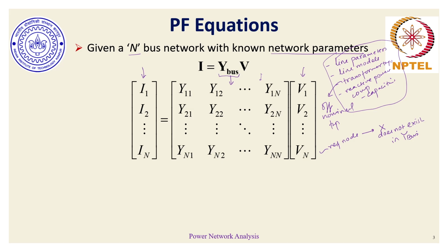So, given this Y-bus, our job is to find a certain set of equations, which we call power flow equations, and from them we will be able to find the corresponding bus voltage phasors. If we know the bus voltage phasors, then we can use Y-bus and voltage phasors to find the corresponding currents at all buses, from where all other relevant quantities can be known.